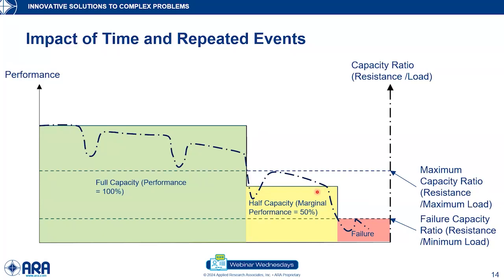And there are two aspects to this if we talk about an embankment, let's say. Rarely would the capacity totally fail, but rather the subgrade is deteriorating over time and impacting the pavements supported by that embankment. But also, again, the capacity of the entire embankment could be a consideration as well.